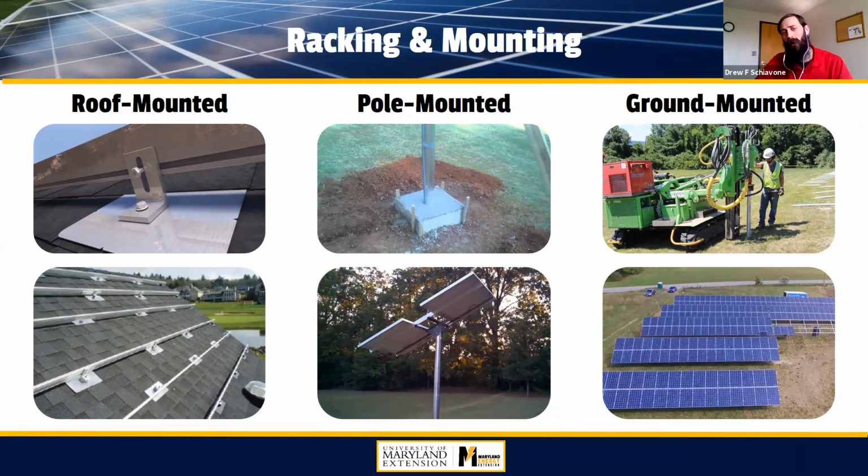Next example is a pole mounted system, and in this case it's a smaller scale system just for one or two modules. This has a concrete footing in the pole, and your conduit's running down through the ground and through that pole. This particular example of pole mounted has a mounting system at the top where you can rotate the angle. So in the winter, you'll have a higher angle on that and you can manually adjust it, or you could have a tracker on it as well.